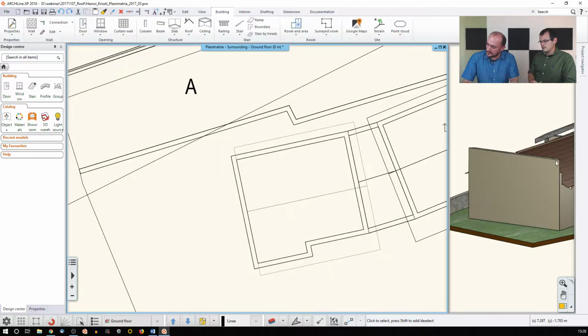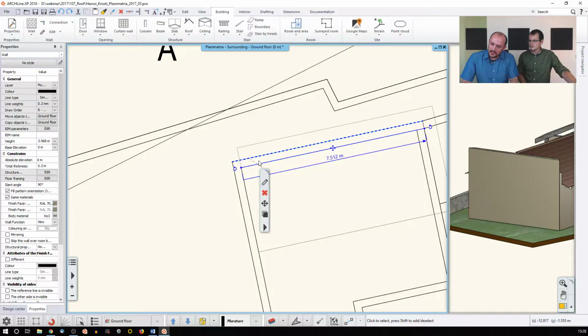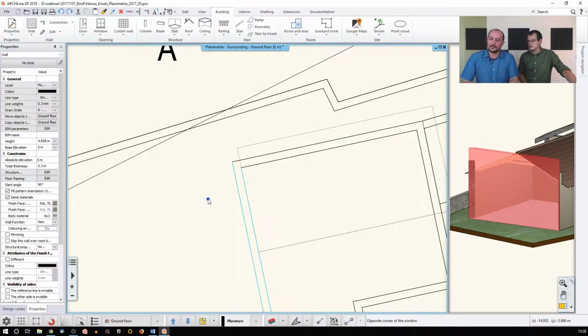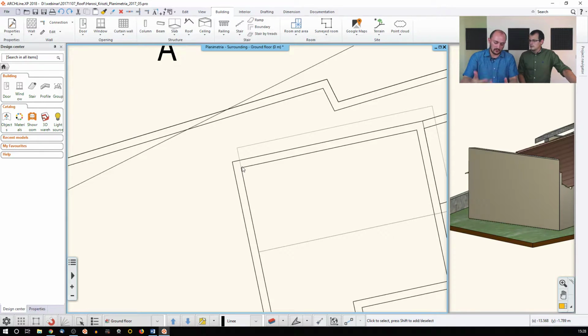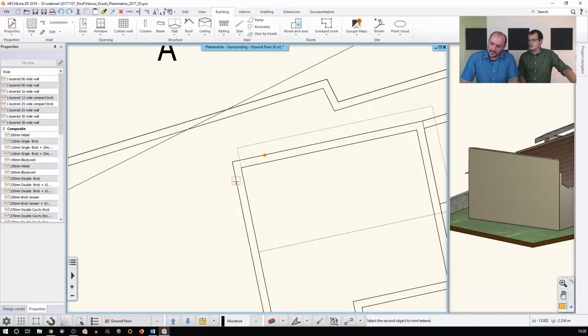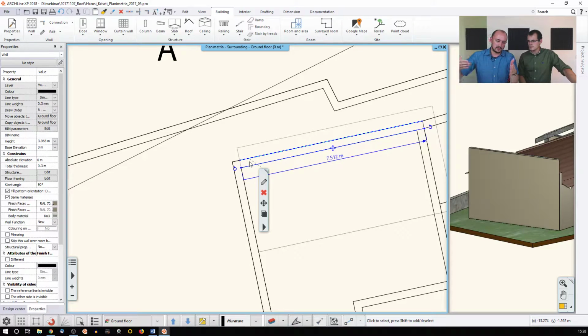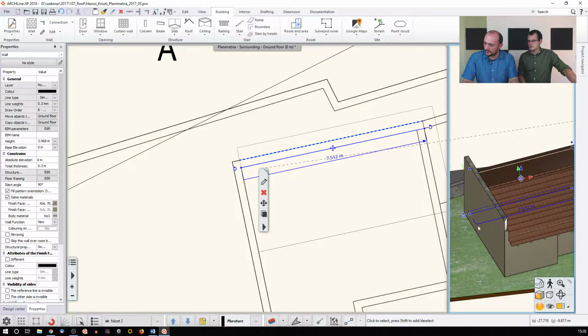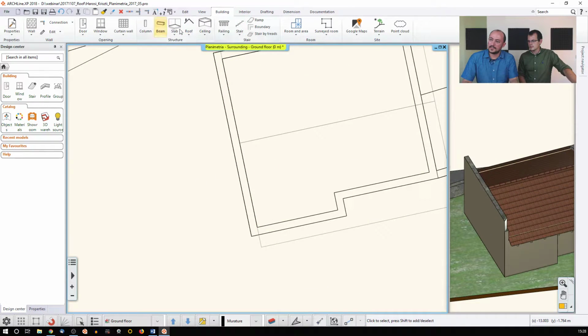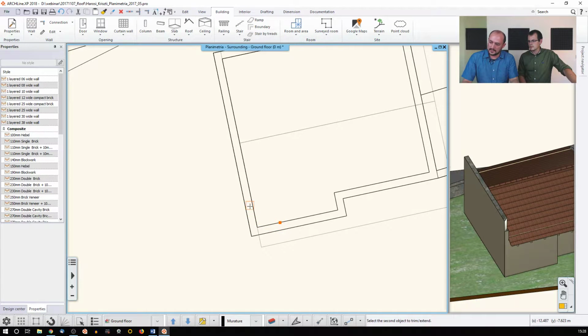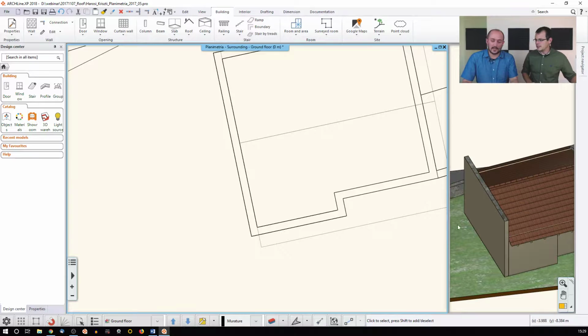The reason it was having this strange connection here is that they are equal in this connection. So it is coming a 45 degree angle cut, a 45 degree angle cut. So there will always be one roof part or one wall part which is not taking part in this connection. So to solve it, you can actually T-connect these together, and in that case this is weaker. It's just bumping into the other wall. And we will see it happening here right away when I'm doing it now. It's a 45 degree angle connection, but when I come here and I say, okay, just T-connect this into this here, yes, then it's solved. It's solved now. So now whatever I do with this wall, it won't have that strange connection.